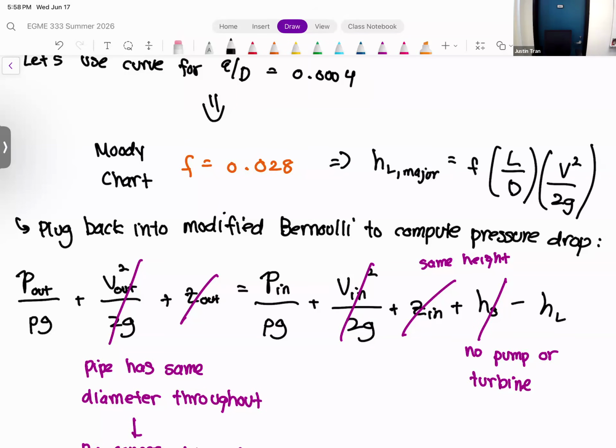But the pressure also, you have the pressure drop. Exactly. Because it just seems weird. It's going at the same speed, but then at the end you get less pressure. Yes, because it's a pressure drop. Where did the pressure go that dropped, the heat, the loss? Exactly. So that pressure energy goes into heat. It was dissipated by the viscosity, basically.